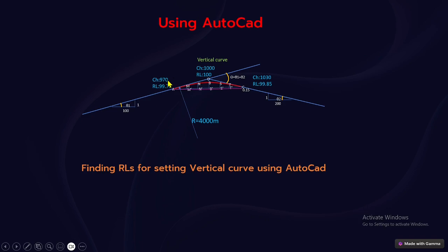From here, taking the measurement, we will be able to get the chainage and RL of the x and y axis. Taking the measurement, we can fix this chainage and RL, and like this, subsequently divide the curve at equal intervals. Selecting the lowest point, forming one baseline, from there we can measure the offset, and after that we can get the RLs of the points which are on the curve. From the base level, measuring the offset and adding it, you will get the RL.